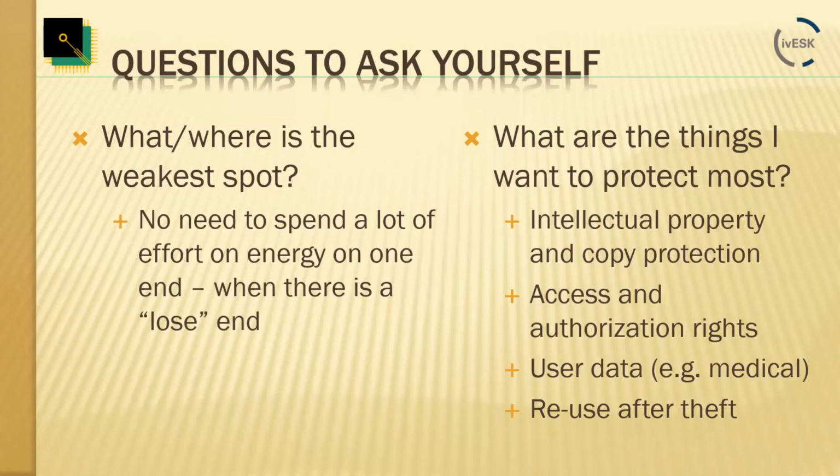So it wouldn't really help if you add a lot of CAN security communication but keep that old bootloader in place. Once that is activated, it's easy: send a hex file there and reprogram. So really, you have to look at all the holes and attack vectors that apply to your system, identify the weakest spot, and then see what you can do about those first before you spend too much effort on other things.